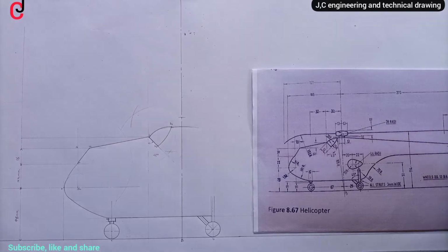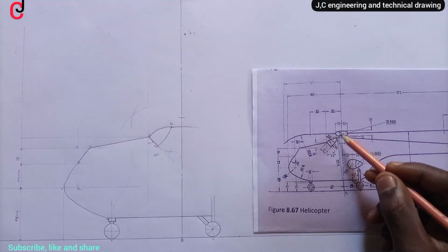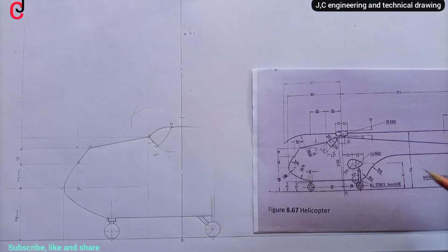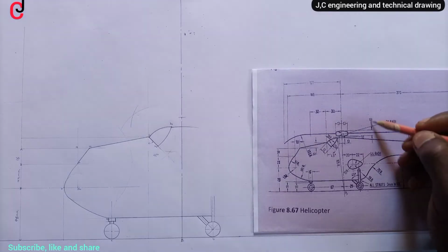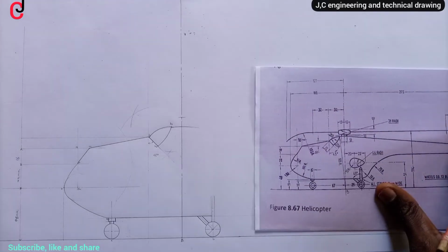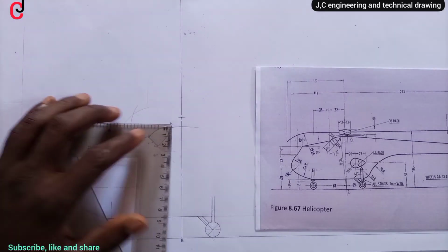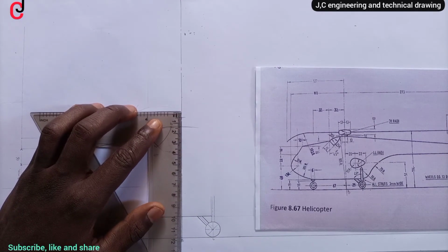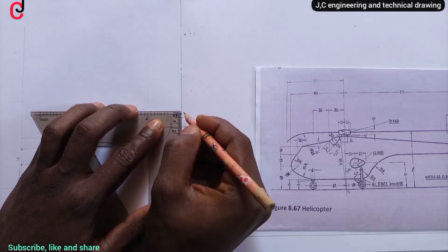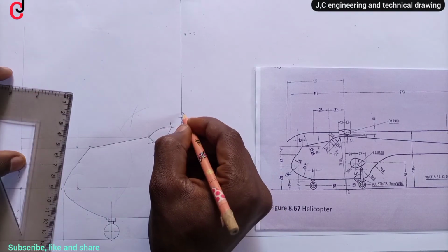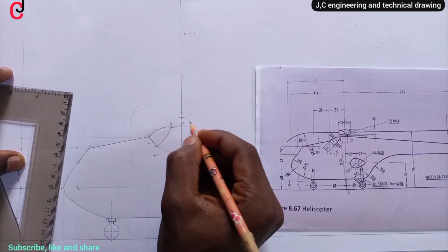Now we know that the total height of our helicopter wing head here is given to us as 10 millimeter. You can see 10 millimeter. So we'll mark on our line from our marked points. Since the total height is given to us as 10 millimeter, we'll pick 5 millimeter upward, we indicate with a point, and then 5 millimeter downward, indicate it also with a point. Call these points 1 and point 2.